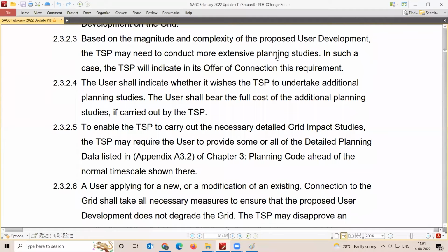Why does the independent power producer have to submit their models even after they are performing the same studies, in India at least? It is because the study has to be repeated by the TSP, right? So you are studying from your end, the independent power producer end, concluding that you do not have any impact to the grid and applying for the grid connectivity. But the transmission system provider has to evaluate this for many other cases. That's the real reason why he is asking for the PSSE model as well as the PSCAD model, to perform the study on his own. And performing the dynamic transient studies is already there. Probably it's an implementation issue rather than whether it exists or not. It exists in India, but it's not implemented properly. That's what I would say.